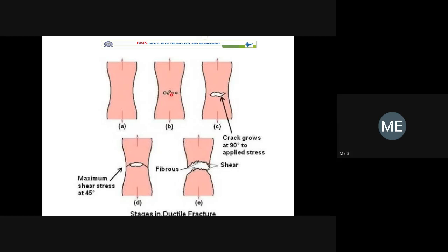So now here we have microscopic voids. Once load is applied, the voids will be formed. These voids will be joined together. These are the microscopic defects or voids. Those voids will be joined together, and finally form a microcrack. If we apply the load further and further, we will get two surfaces. The amount of energy spent to generate additional surfaces is nothing but your fracture energy.